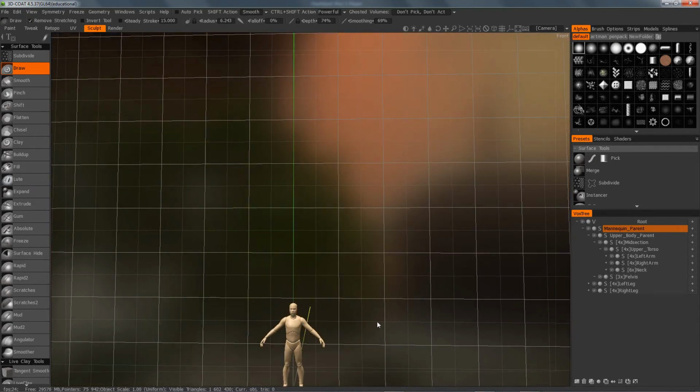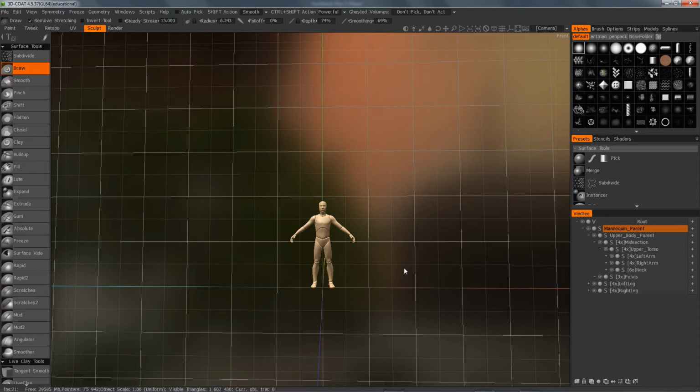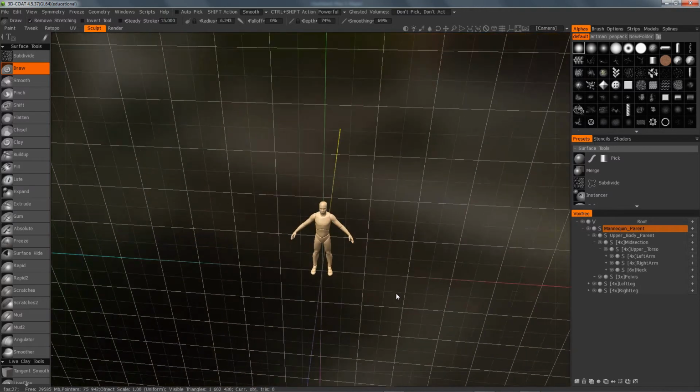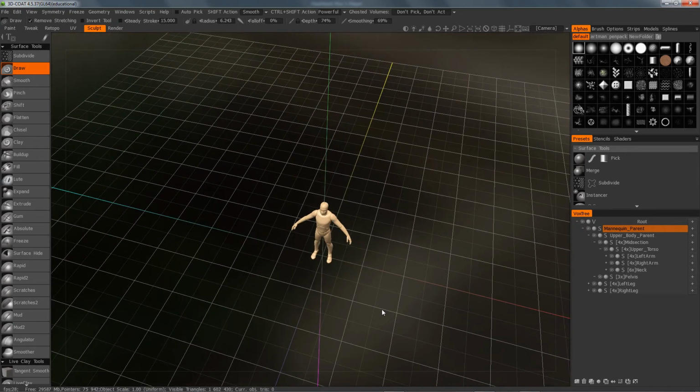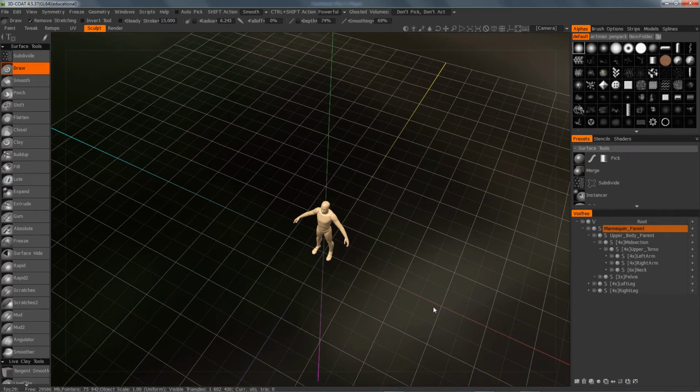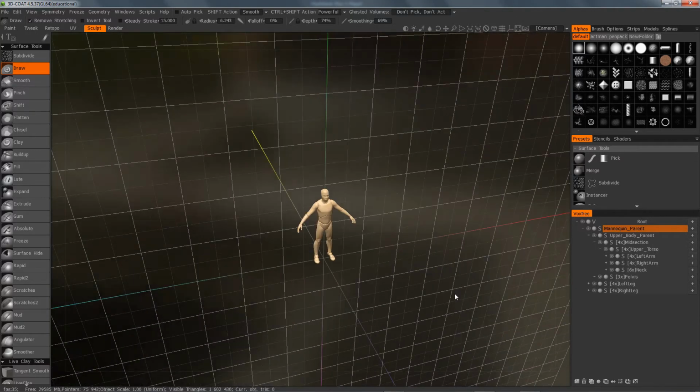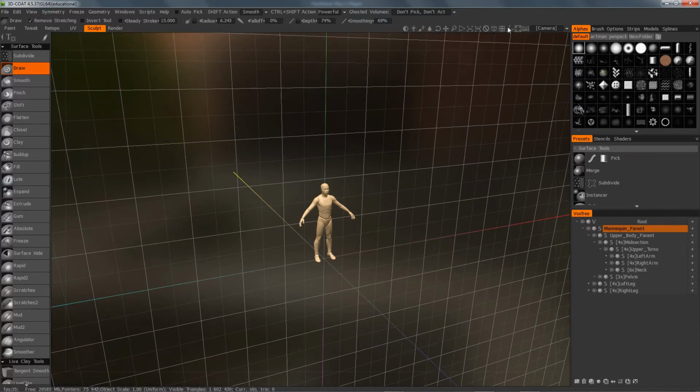Now in Rhino that would be true if this were the front C-plane and you were using local coordinates, which is pretty advanced Rhino speak. In 3D Coat it's consistent, it's always that way. So if I rotate this so that the top grid becomes apparent, those axes stay the same. Red for X, blue for Z, green for Y. It is interesting that they use the complementary of the color going away the other direction. I really never have a reason to show that, except for this tutorial where it's kind of nice.